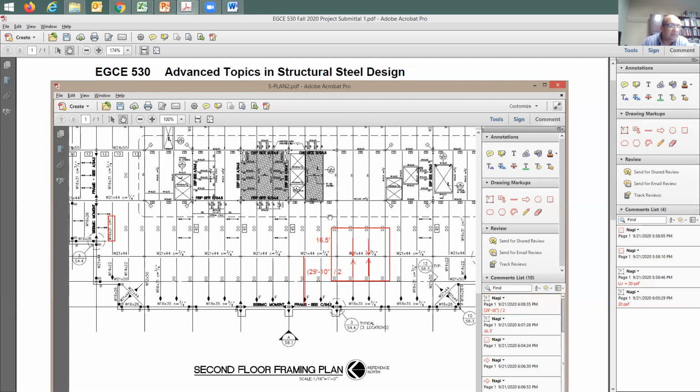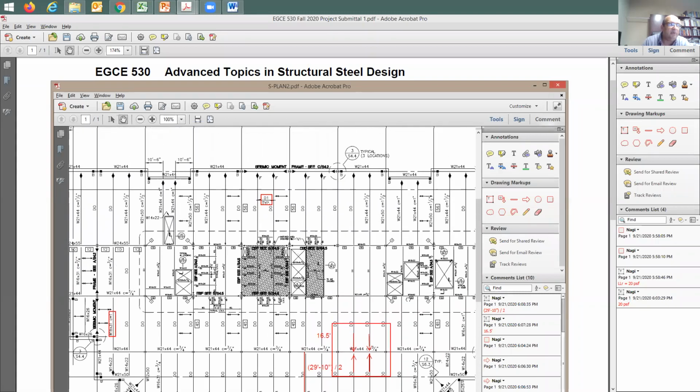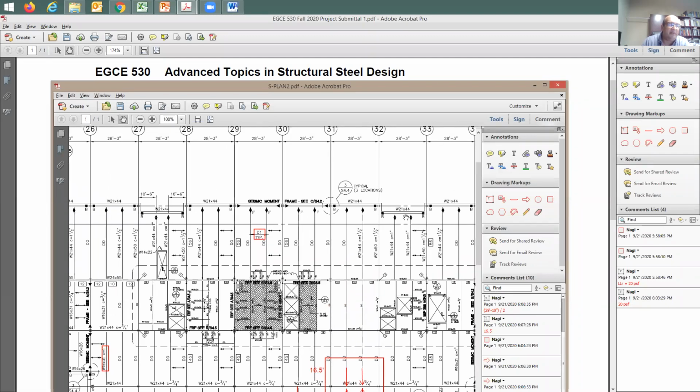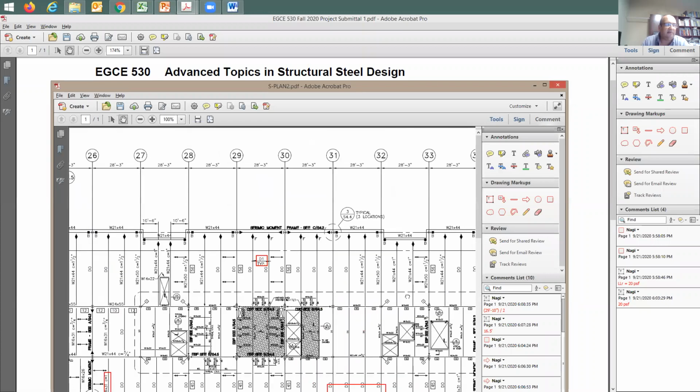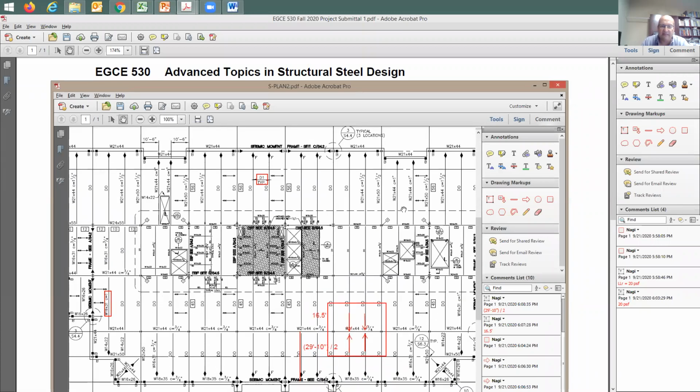So what you need to do, you take the half of this distributor width, you take the 16.5 plus the other number from here, and this gives you the flange width. But you have some other numbers to control it, which is 1/4 of the span. So you're going to be taking these two numbers, you add them, compare them with 1/4 of the 28 feet 3 inches, which is going to be about, let's say, 7 feet, roughly.